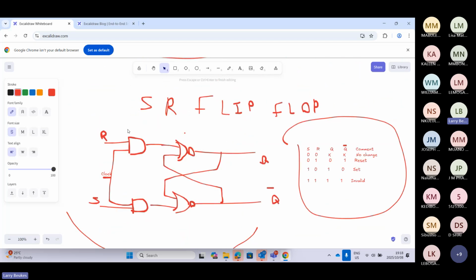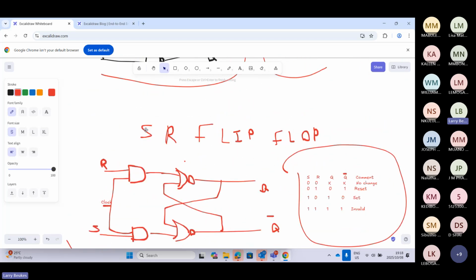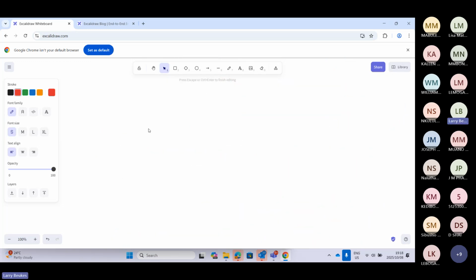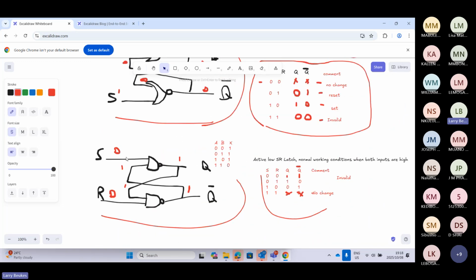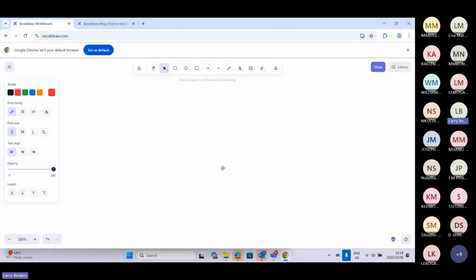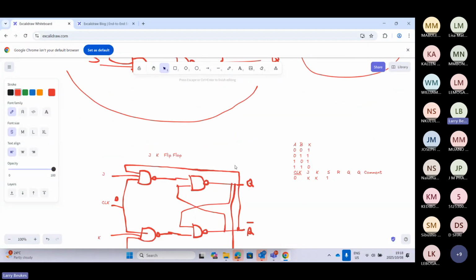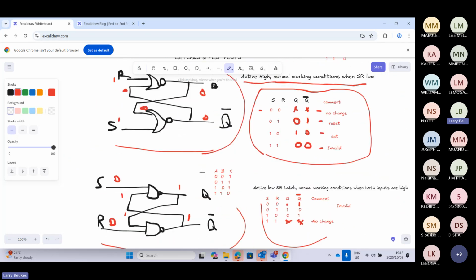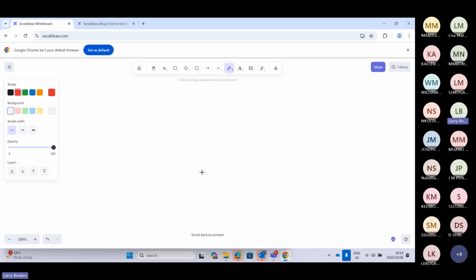Remember, this was the one of the NAND gate. The value of S will be 1 and the value of R will be 1, right? It will be 1, 1. You will be in this case, right? Look at this. With just 1, 1, 0, the clock. So this will be 1, 1. Why are we saying that? Because in an AND gate, the output will be 0, but in a NAND gate, the output will be 1. So we know this will be 1, and then this will be 1. It takes us back to that condition of this gate.